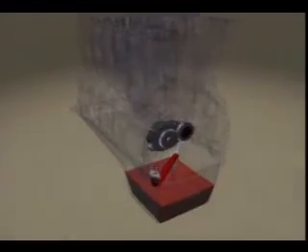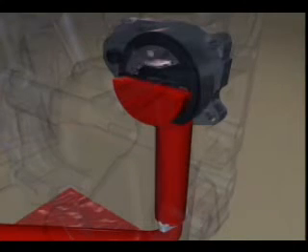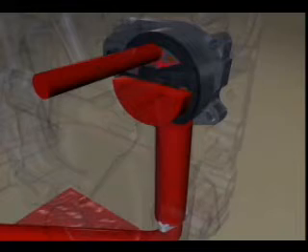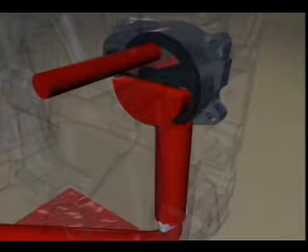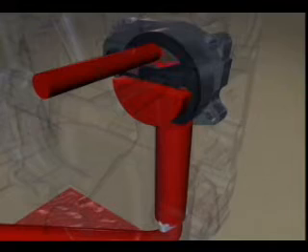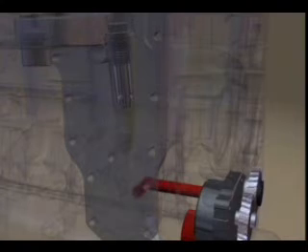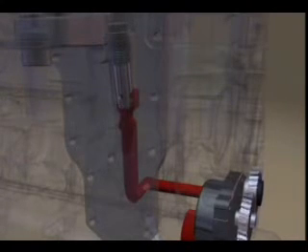The suction tube delivers oil to the gerotor lubrication pump. The unique oil pump installed in the front gear housing utilizes hollow gears in the pumping chamber of the oil pump for improved pumping efficiency at high engine speeds. The pump then delivers the lubricating oil through an internal drilling to the oil cooler cover and the pressure regulator.